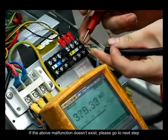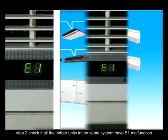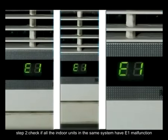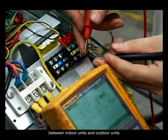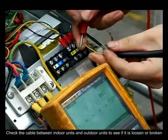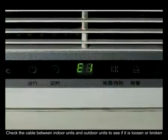If the above malfunction doesn't exist, please go to the next step. Step 2. Check if all the indoor units in the same system have E1 malfunction. If so, the malfunction should be caused by the communication cable between indoor units and outdoor units. Check the cable between indoor units and outdoor units to see if it is loosened or broken.